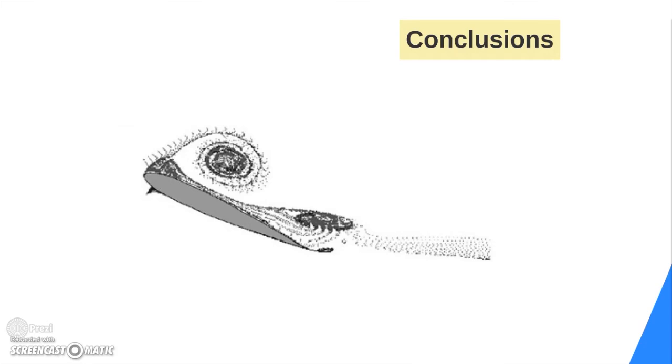And 4. At lower rotational speeds, the aerodynamic stall characteristic of the turbine significantly reduces the output power capability at high mean pneumatic power levels, while at low mean pneumatic power inputs, lower turbine speed enhances the power output.